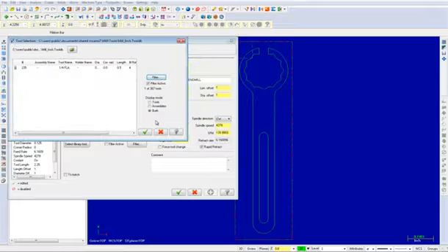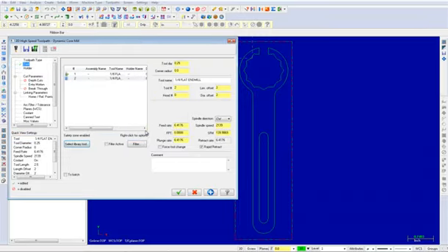In the Tool Selection dialog box, you should now only see a 1/4 inch flat end mill. Select the 1/4 inch flat end mill in the Tool Selection page and then choose the OK button. Your tool will appear as shown. Input the following comment and then select the cut parameters.